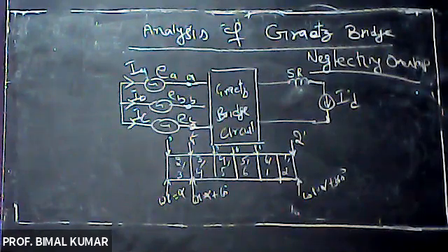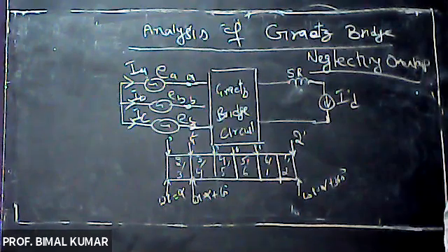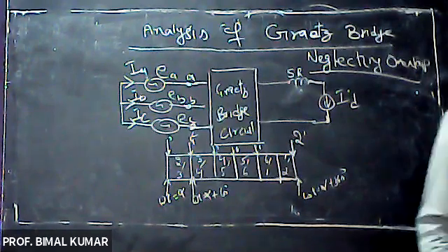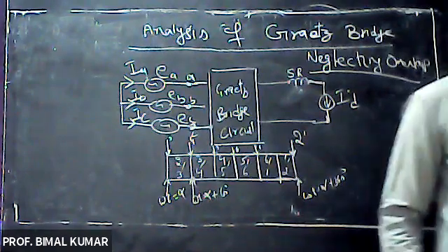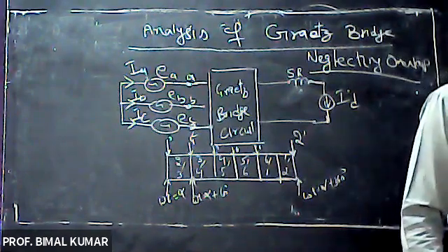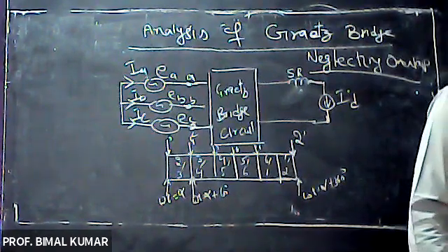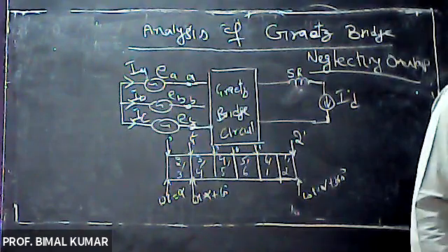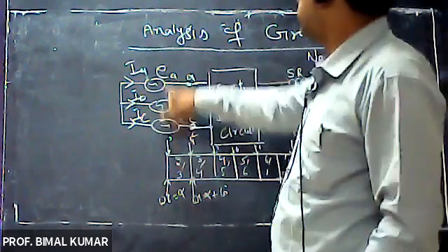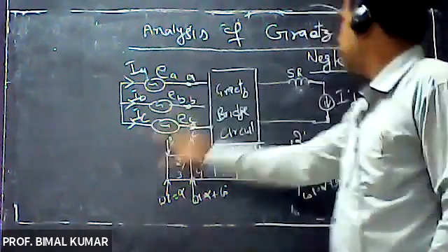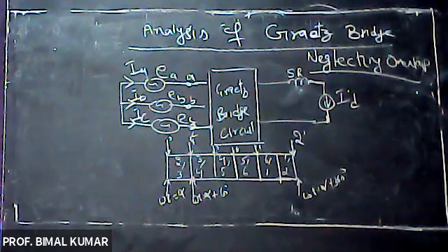In the case of the LCC, line commutated converter, the Graetz bridge is connected to three balanced sinusoidal voltage sources on the AC side and a constant DC current source on the DC side.